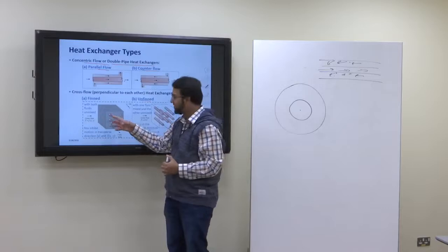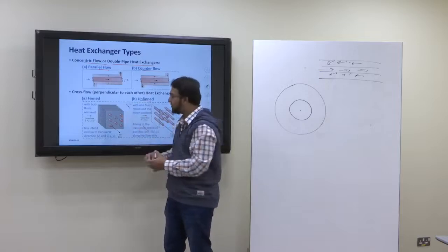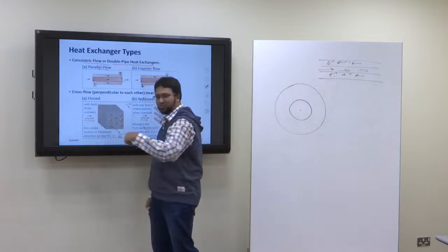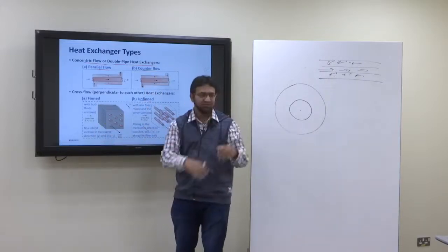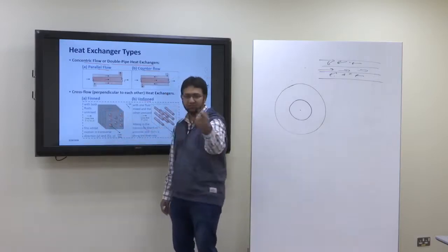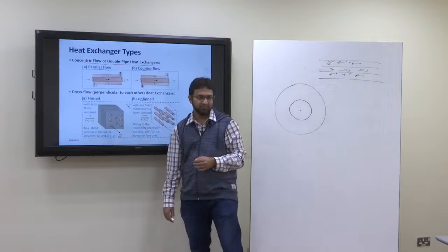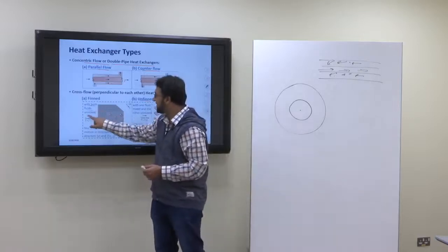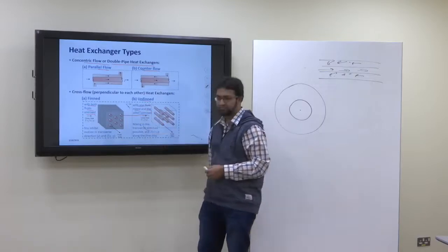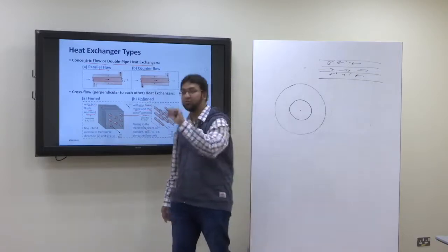On this side, if you see here, flow through the pipe, do you think it is mixed or unmixed? Unmixed. What about the flow through these tubes, these fins? This is also unmixed, because now you put the plates parallel, so any fluid which enters one of the gaps will not mix with the other fluid until it comes out of the heat exchanger. Okay? So this is with both fluids unmixed. This is with one fluid mixed and the other unmixed. This is another classification. This is actually a very important classification for the case of cross flow heat exchangers.